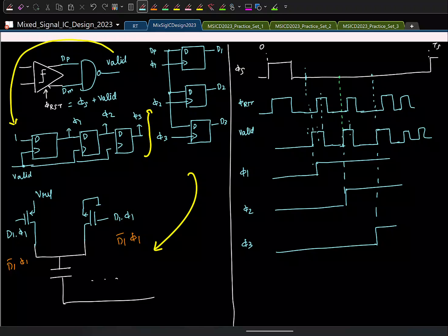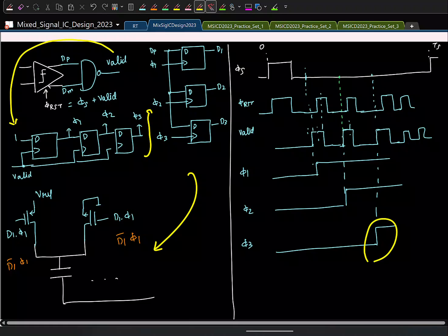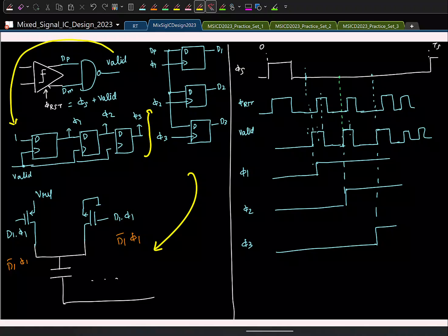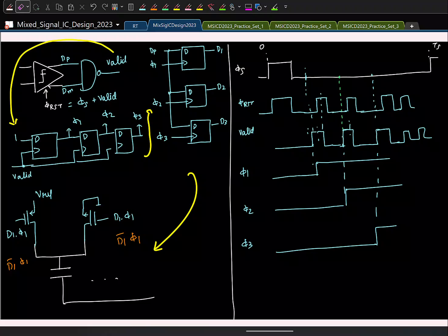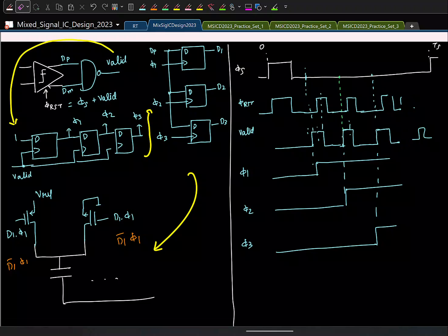But you don't want it to repeat after we finish the third comparison, right? Because it's unnecessarily firing the comparator. So once the third comparison is done, you better go and reset the comparator for all, right? That way the comparator will not be doing anything. The outputs will be at VDD. So I will not let this thing happen continuously.